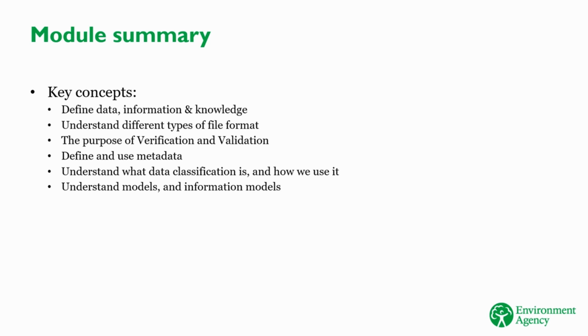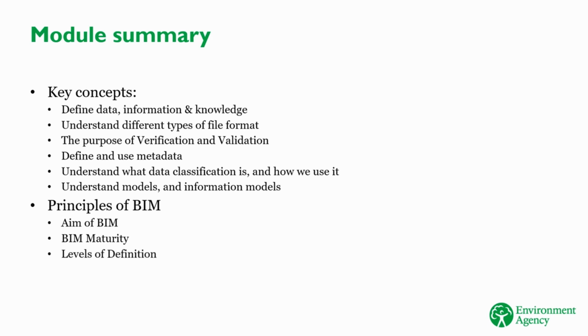You've also learned some of the key principles of BIM. That BIM is not just about 3D modelling. It's about collecting data and information to help us operate and maintain our assets. The levels of BIM maturity used to explain BIM adoption. That level of definition is used to specify how well developed a deliverable needs to be, in reference to the project stage. How to use volumes and locations to classify data and information. And the principles of COBie for data exchange.